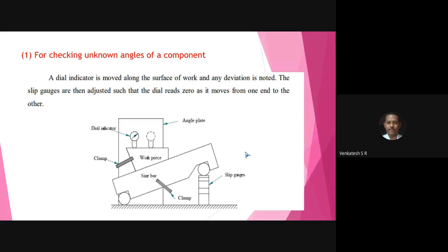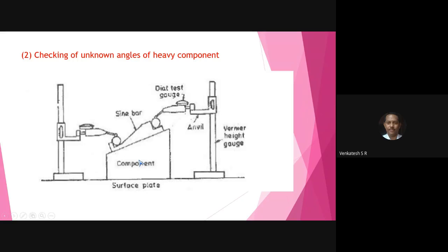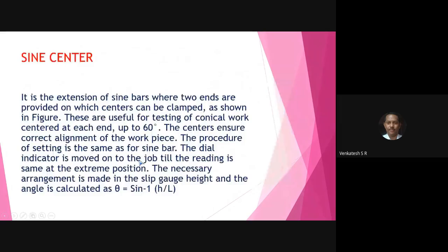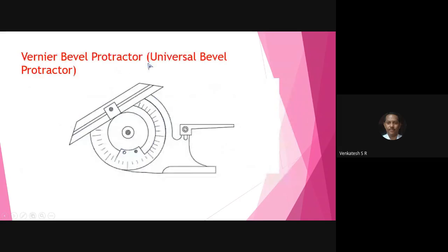But in this case, first you measure the taper of the workpiece using a vernier bevel protractor or universal bevel protractor.